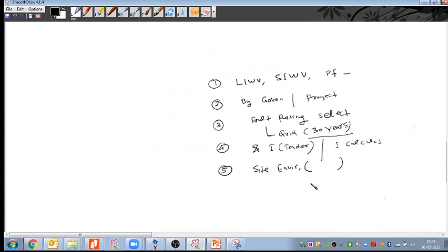And we have done some simulations: if my installation height increases by 100 meters, there is a 2% drop in the equipment capacity. And why does this drop happen? Because the air density is less, heat cannot easily dissipate into the environment, so the equipment rating will decrease. That is the point. And then we discussed that if temperature increases, every 1% temperature increase will derate equipment by around 1%. This we discussed with the help of ETAP.